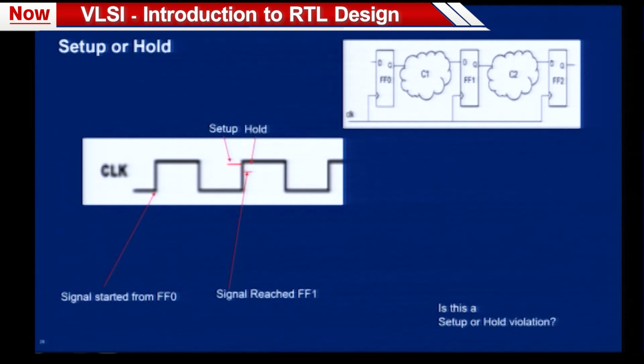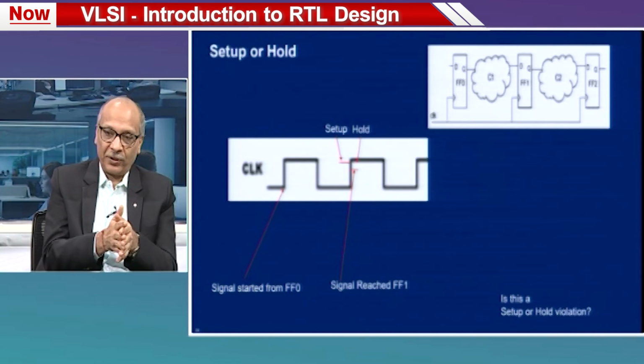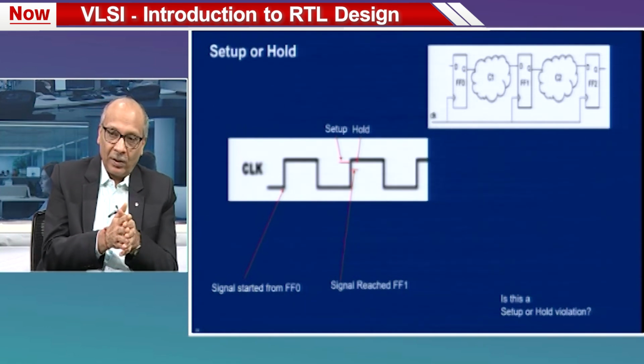As per STA, this is a setup violation because the signal did not reach setup time before the clock edge. STA says the signal should have reached before the setup time before the clock edge. The signal did not reach at that time. It does not matter when it will reach after that, but it did not reach till that time, so it is a setup violation for STA.